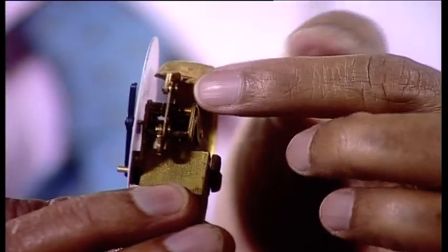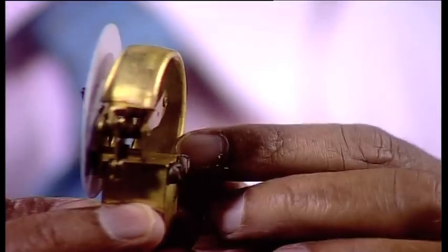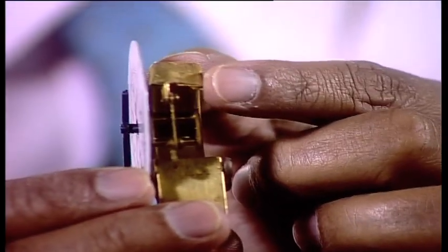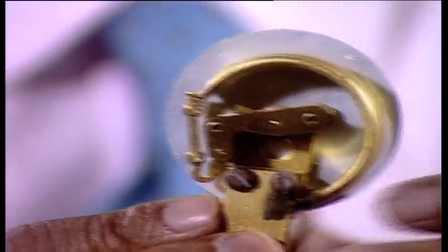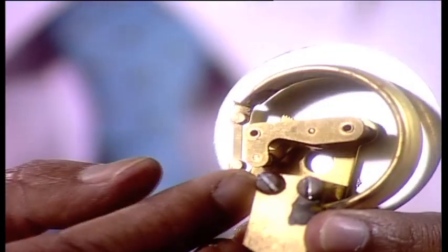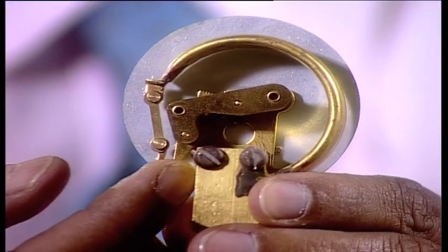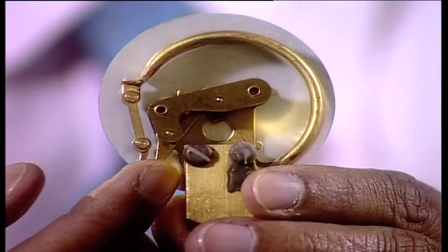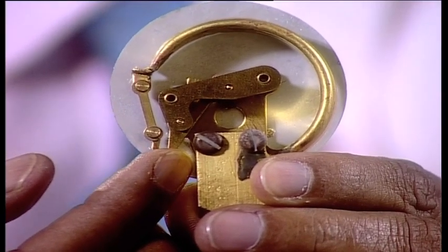You see this is a closed end, it is sealed here, because this is a typical C type Bourdon tube. So, this is the sealed end, right. And here, now you can see the sector, again I will show you. You see the sector is moving, okay, the C tube is coming down, and we are getting the movement.